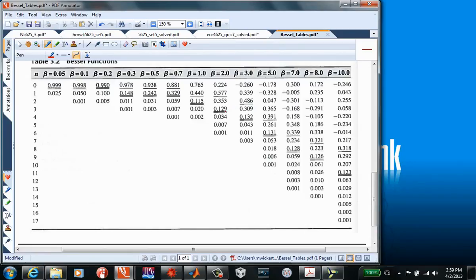So this is 3 sidebands, that's 4. It's still hanging out at 3 at 2.4048, which would be stuffed in the middle here. There's not an entry for 2.4048. But for 2, you're using the carrier, first pair, second pair, and up through the third pair to get 98%.